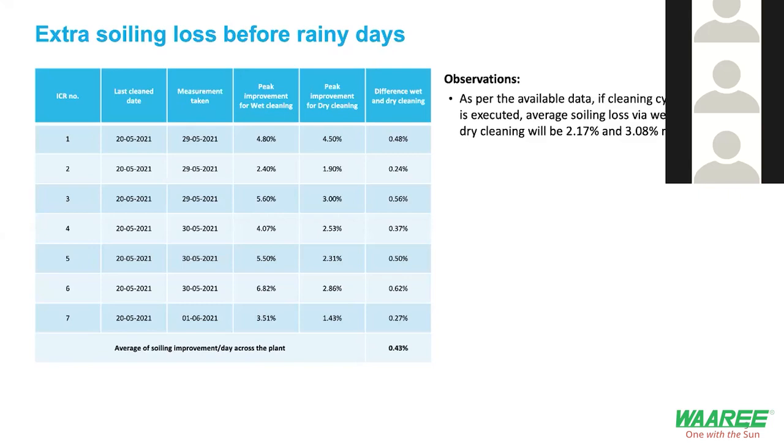A lot of developers ask us to take up O&M for soiling level issues for rooftop plants, because everyone is facing issues, and since budgets are very low, the cleaning cycles cannot be higher. That leads to the end issue. So what I would share with everyone is that if you are doing rooftop plants, do consider that the soiling will be higher, and you should also consider higher budgets at the start of the plant life itself, during the inception and discussion stage.